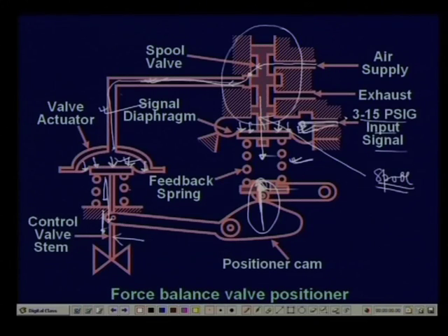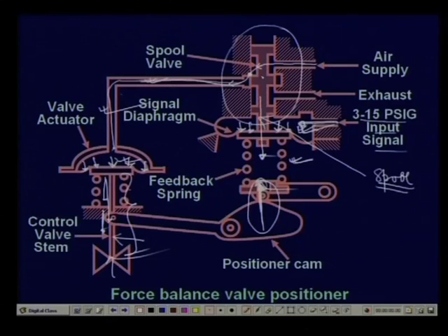So, when you apply a particular pressure here, a particular displacement of the stem is achieved, irrespective of what the forces here are. Till this displacement is achieved, this will keep moving, and obviously this should have enough power to overcome this force. But if you have created enough power, then just enough force will be created here so that the final displacement will balance this pressure.